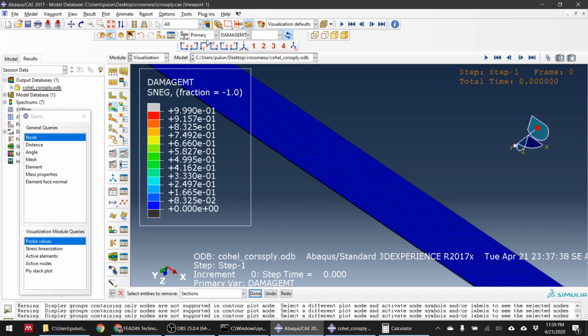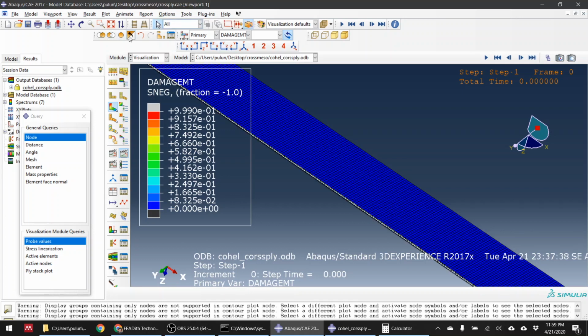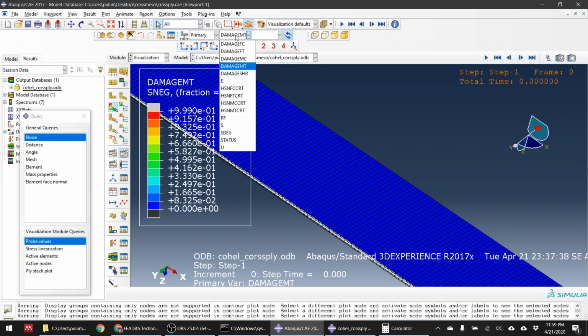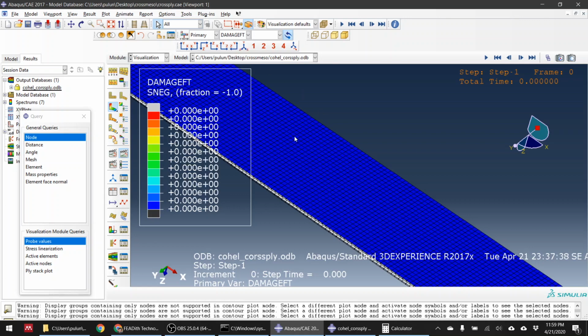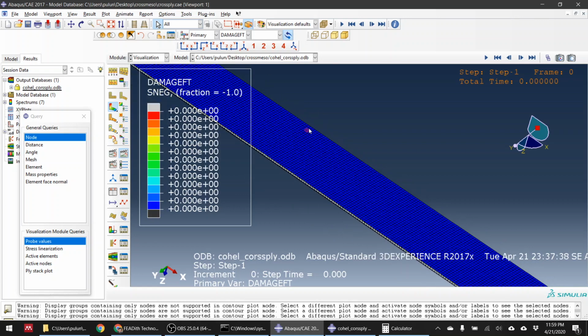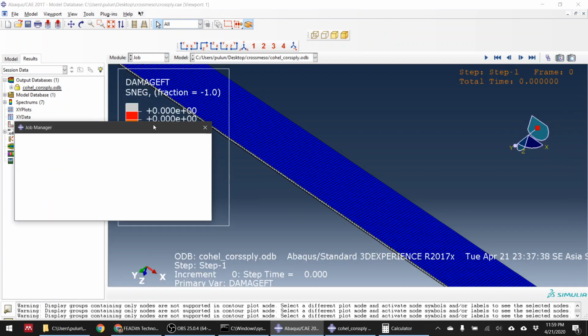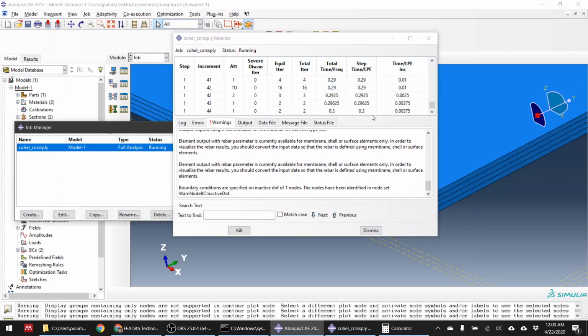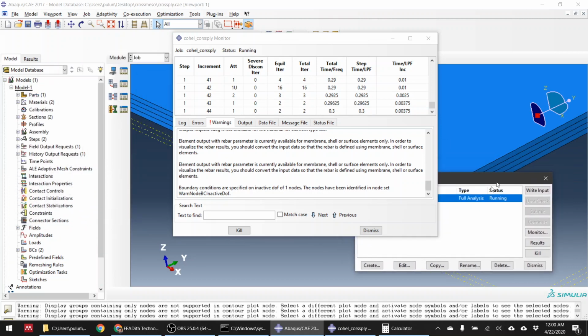But the fiber itself, up to now, is not yet damaged, because to make it damage, you need a 2.2% applied strain, while the simulation now is still reaching 30% of 3%, so it's 0.9, so it's still far from damage. But I think if you wait enough, yeah, it will be damaged later.